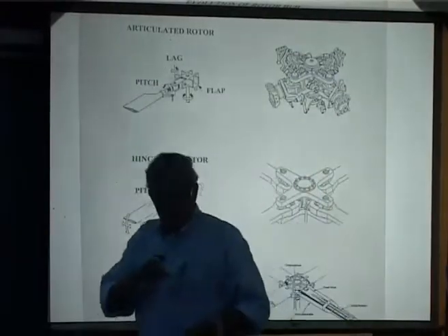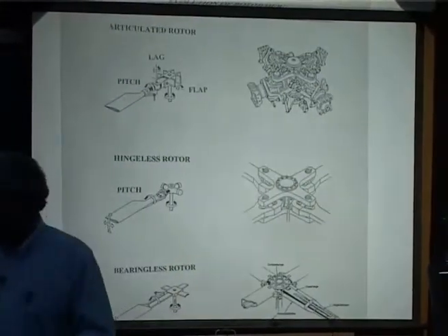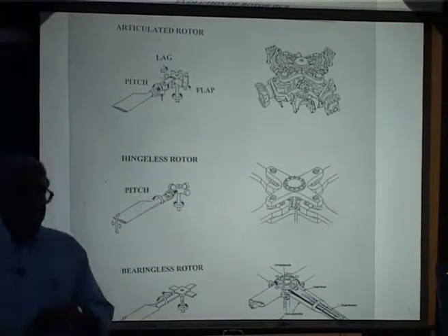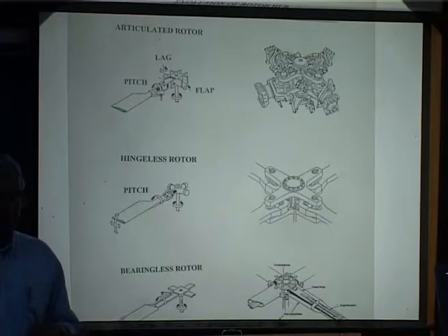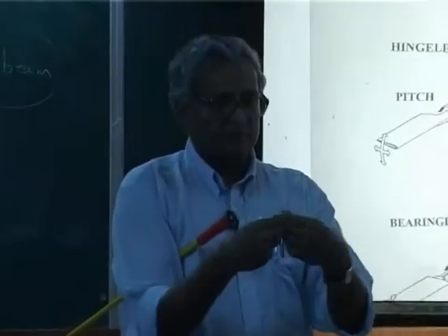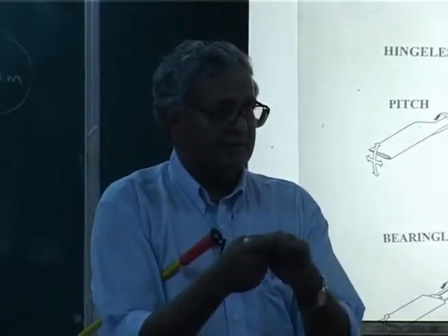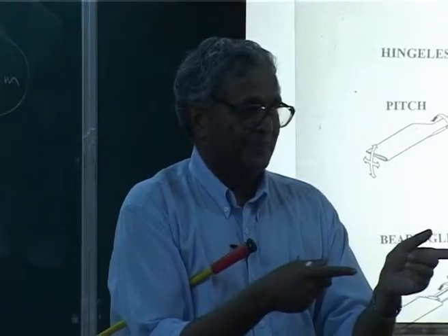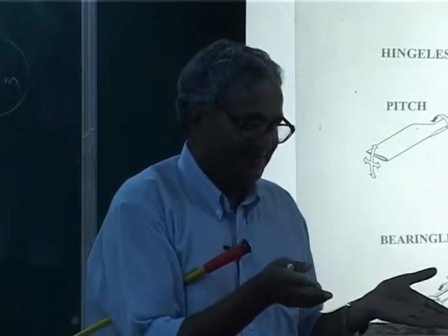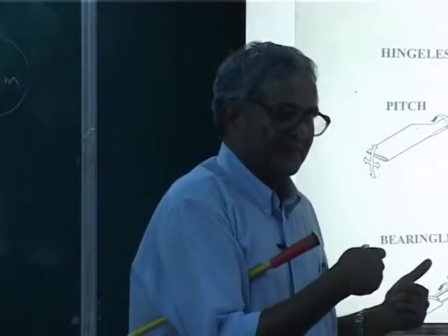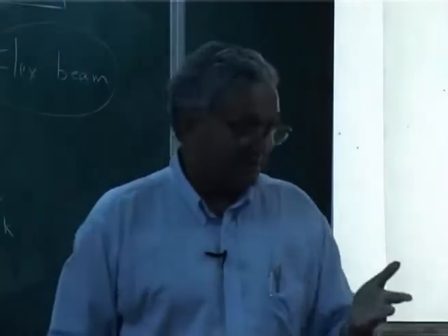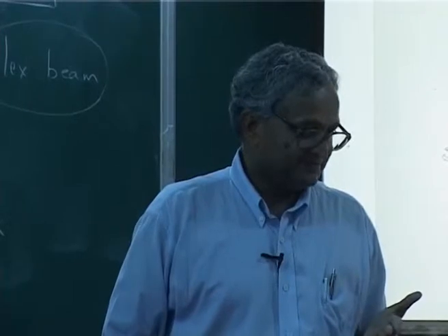No, there is fatigue damage. See, fatigue is always there. Suppose you say hingeless blade, you want it to flap up and down, right? Suppose you take a pin, you want to break it, what do you do? You keep doing like this, and then it will break. That is fatigue. Here, fatigue is very important, but you don't want the blade to break, which means you have to design such that the fatigue life is what is mandated, what is required.